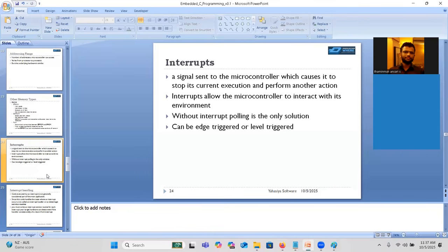We lost the memory address 1000. After completing the interrupt service routine, how does the program counter know about the old address? Do you understand my question? See, when it was running the infinite loop, the address in which it is running is the program counter value 1000, because in memory location 1000 we have the infinite loop. It is running that. The moment we got a valid character from the computer to the receive register of the microcontroller, it generates the interrupt. That interrupt loads program memory address 5 to the program counter. Now the 1000 is lost. We didn't store 1000 anywhere.